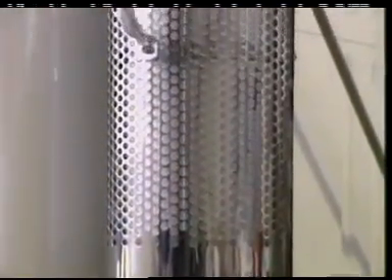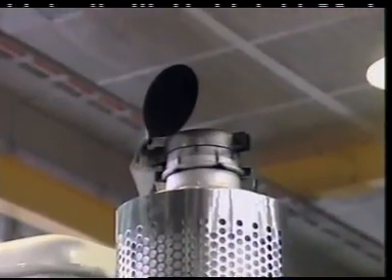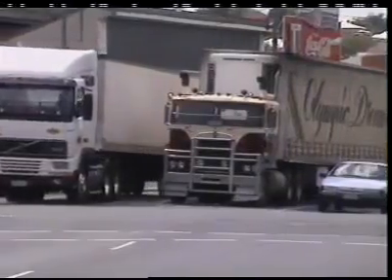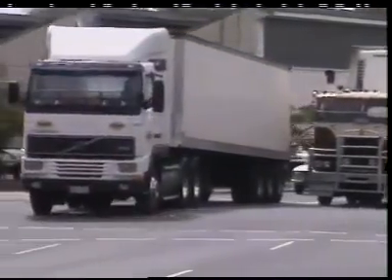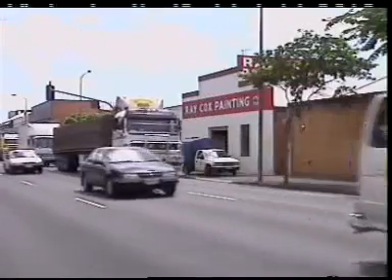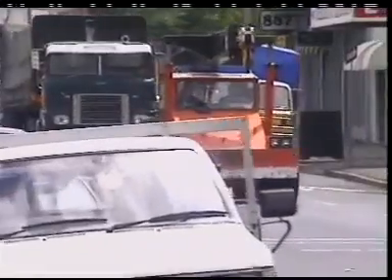Diesel engines are usually low in carbon monoxide and hydrocarbon emissions, though some do emit high levels of the oxides of nitrogen. The main problem with diesel engines is the emission of particulates, minute particles of carbon visible as black smoke. Most diesel engines of heavier vehicles use electronically controlled injectors. This has reduced considerably the emission of particulates and oxides of nitrogen.